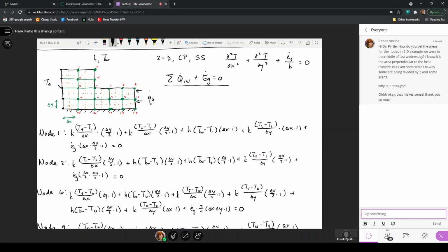Because if this temperature is a constant and convection is occurring, with all the generation that's occurring in the material, the heat is going to leave through the boundary that is at TA, through the boundary where we have the heat transfer by convection. And if heat transfers from a high to a low temperature, if I'm putting heat in on this far right-hand boundary, then all the heat that comes in is going to move out of these surfaces on the left and on the top, or the upper surfaces here.